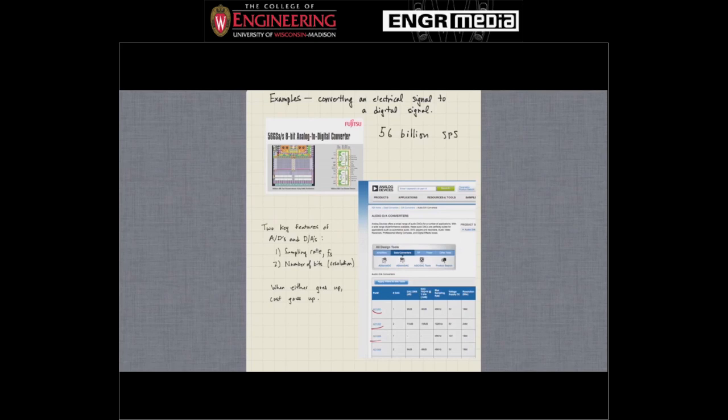But the key things are, let's see here, the sampling rate. It's written as the maximum sampling rate, and you can see the first one is 48 kilohertz, so 48 kilosamples per second. The second one's 192 kilosamples per second. And again, these are D to A converters. So this is the rate at which they're able to recreate an analog signal. It's the rate at which the samples are output from the device with a continuous time waveform.